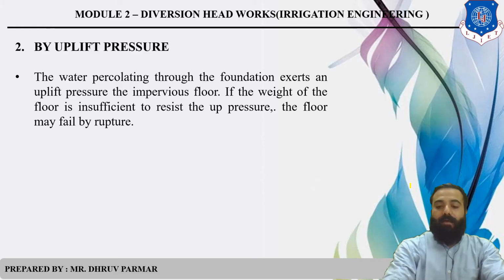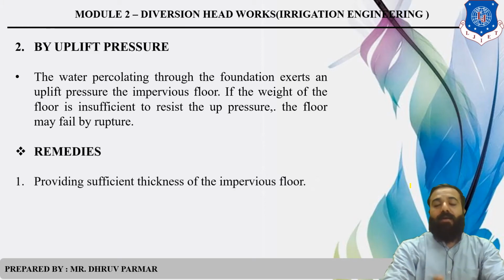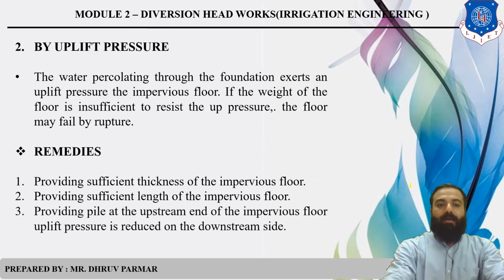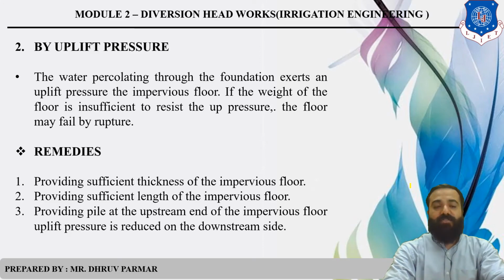So in this condition, what are the remedies? First, you can provide or increase the impervious floor thickness. Second, the length of the impervious floor should be sufficient to resist uplift pressure. And third, you also provide a pile at the upstream side of the impervious floor to reduce uplift pressure on the downstream side. So these are the three remedies used to minimize this condition.